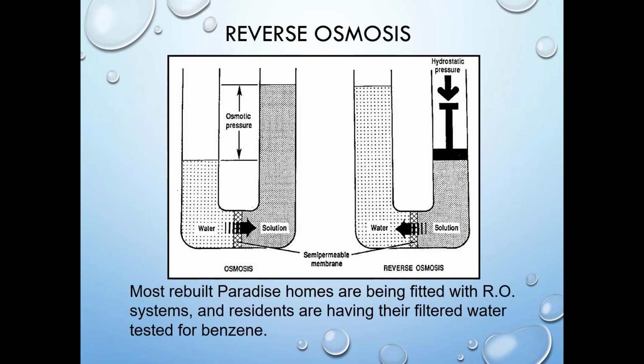In reverse osmosis, the idea is that you are trying to force all of that to happen backwards, the other way. So you're starting off with a higher amount of that concentrated solution and a fairly low amount of that less concentrated water side. And this has what we call osmotic pressure. Now, if you apply pressure to this side, then you can force the solution through, right? It would really be that you're forcing the water molecules through this semi-permeable membrane. It has pores large enough to let water molecules through, but small enough that whatever contaminant you're trying to keep on this side can't pass through. Okay, so you just apply pressure, and then gradually you get more and more water. Okay, so that's reverse osmosis.